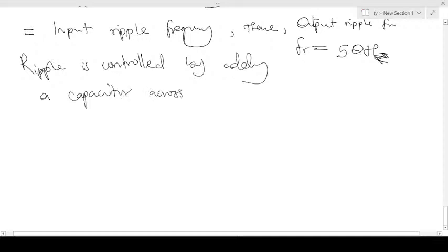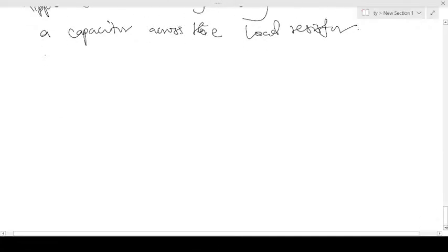This capacitor will help us to filter the voltage, producing a much more desirable effect. So that's something to keep in mind for the future: due to the extreme ripple effects on half-wave rectifiers, a capacitor is used to filter the voltage, producing a much more desirable effect.